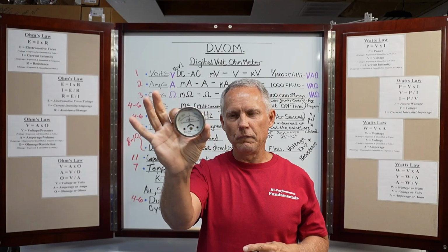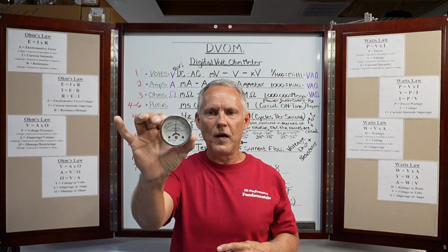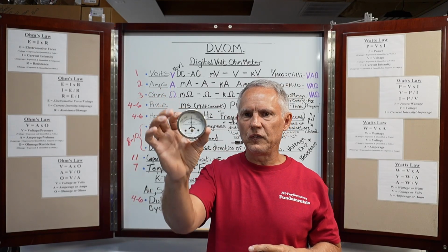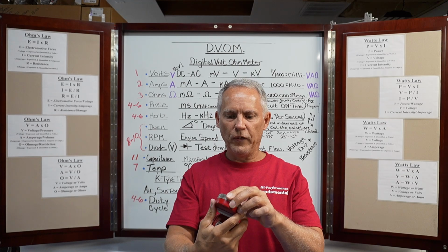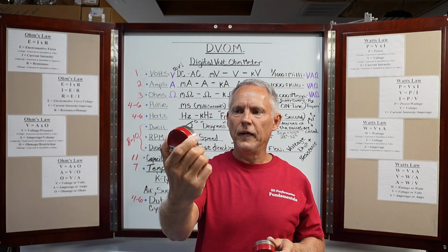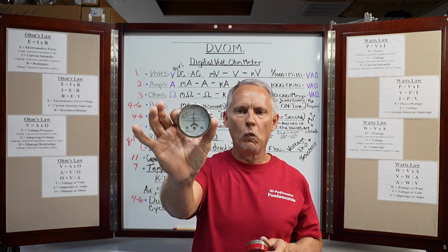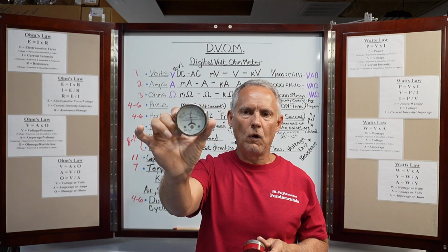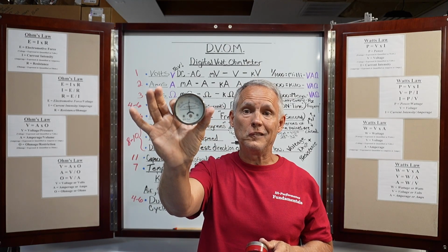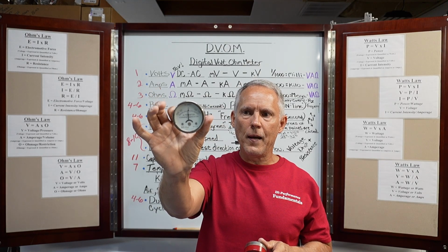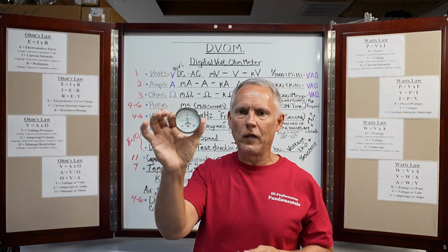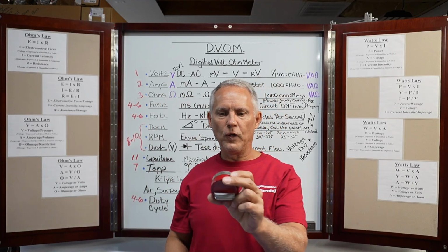I've had these for a very long time. I've been doing this for a long time. This one measures up to 600 amps. This one is labeled as an alternator current tester, and it goes up to 100 amps. Now, if you work on alternators, you know that nowadays alternators can be a lot greater than that, 160 amps, but this one goes to 100 amps. Doesn't matter what it says on it, it's good up to 100 amps. This one's good up to 600 amps.